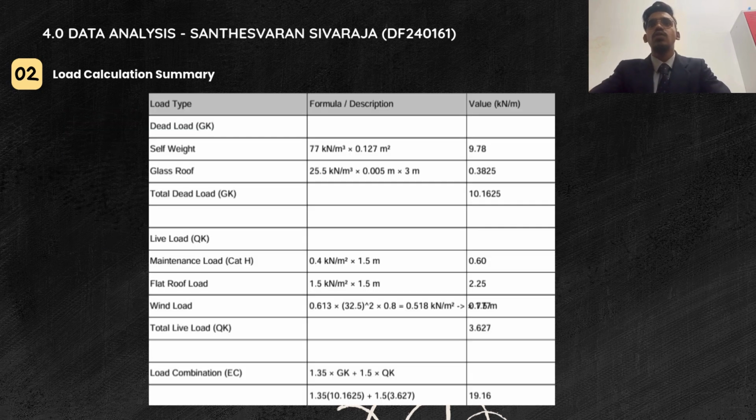Next, we move on to the load calculation summary. This step is essential to determine the types of force acting on the beam. We calculate both the dead load and live load acting on the structure. These values are crucial for computing support reactions and further structural responses like shear force and bending moment.